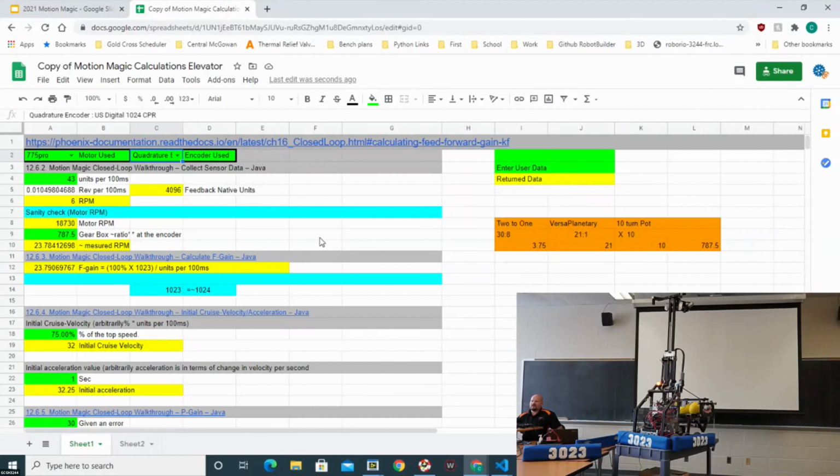In FIRST, I don't think it matters too terribly much. Now, with the drivetrain, that is an absolutely true statement, just because we're trying to position a robot, drive some distances, and there's all the backlash. So if you put it on the output shaft, you get rid of all that backlash because you're measuring the actual device.